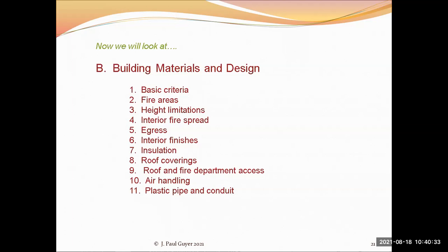Roof coverings, this is important, a concept to keep in mind, because what you might call the heat vector of a fire is straight up. That's just the way fires burn. The hottest part is pointed to the sky, and so the roof of the building is particularly important that it have a high level of fire resistive construction because first of all, it's under the greatest heat stress probably, but also with roofs, a particular danger there is that in the event of a fire in a building, the fire breaks out of the roof.